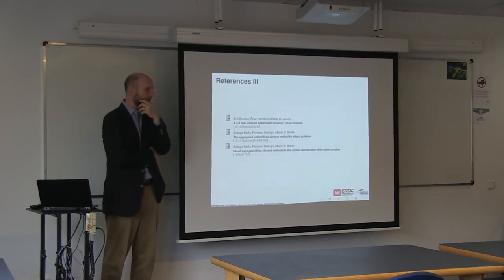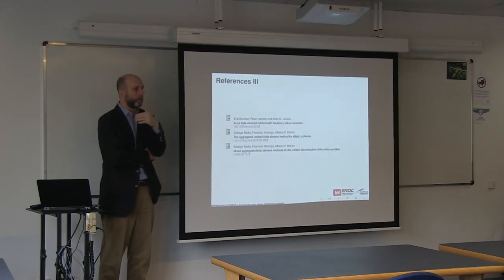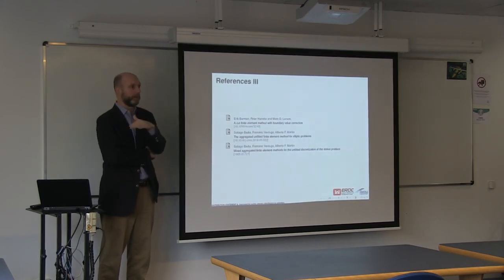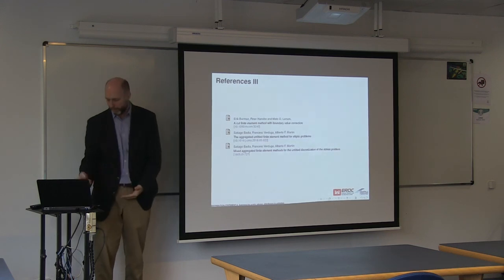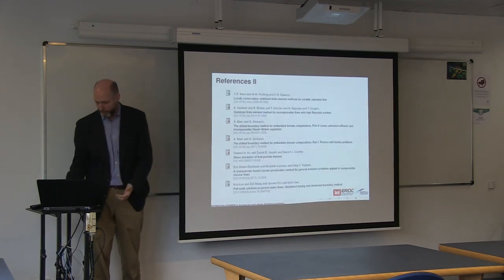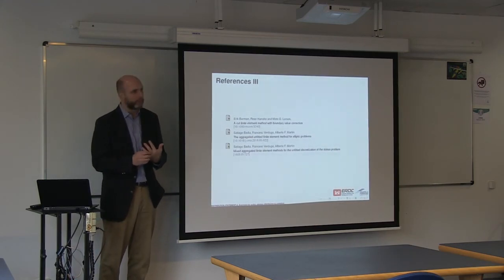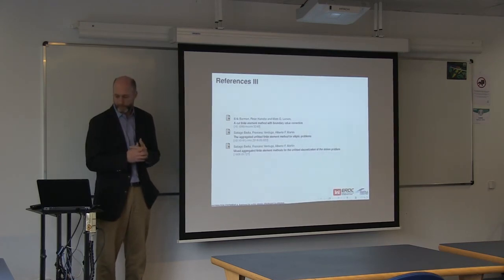I think of the time averaging coming in the same sense that you do time averaging when you're dealing with a turbulent flow. At the end of the day, you can't resolve the temporal dynamics in a practical manner much better than you could manage the spatial variations at the microscale, so you end up averaging over both. I don't have the references in my talk slides here, but Vladimir Nikora, I think, in the UK has done a lot on doubly averaged flows like this, both for moving beds and also for fixed beds where this is important.